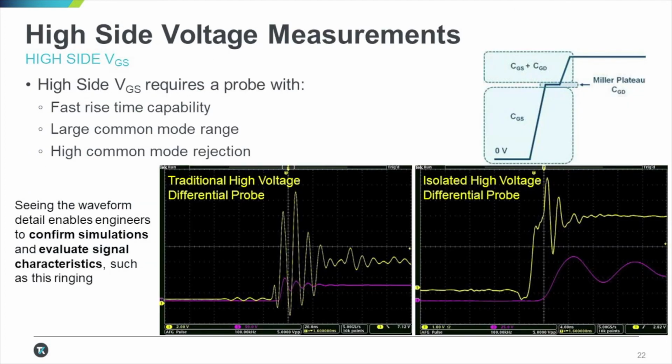I wanted to touch base on Tektronix's focus and expertise in high-performance probe solutions, particularly for those in the audience that are working on higher frequency, higher power switch mode power supplies that are now more commonly using silicon carbide or gallium nitride semiconductors. Tektronix has a one-of-a-kind solution, which is a galvanically isolated differential probe that provides absolute clarity of high differential voltage measurements in the face of very high common mode voltage.